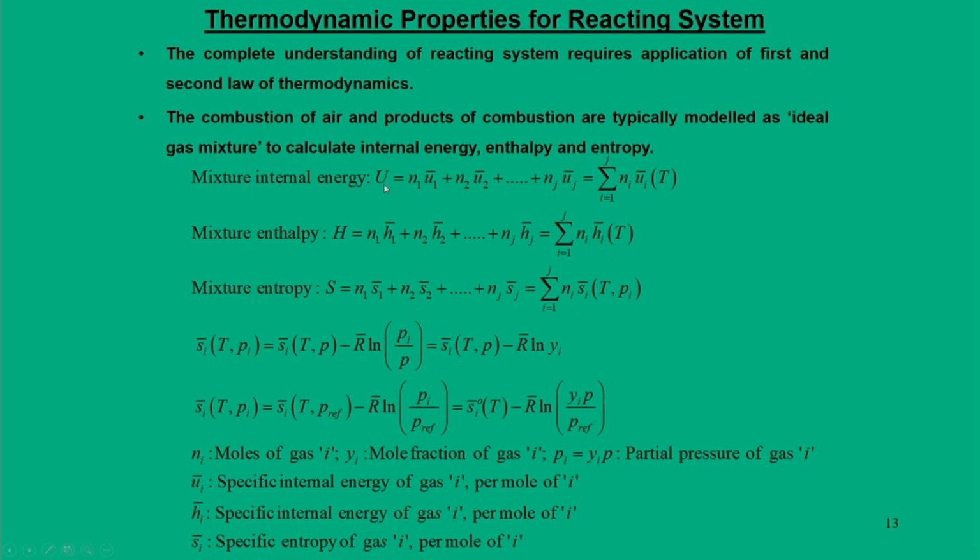For example, internal energy is the summation of the molar specific internal energy multiplied by the mole fractions for all the components, and the same logic applies for enthalpy as well. Now, for entropy a similar philosophy is used, but entropy is calculated at temperature T and pressure, because it is a function of temperature as well as pressure.